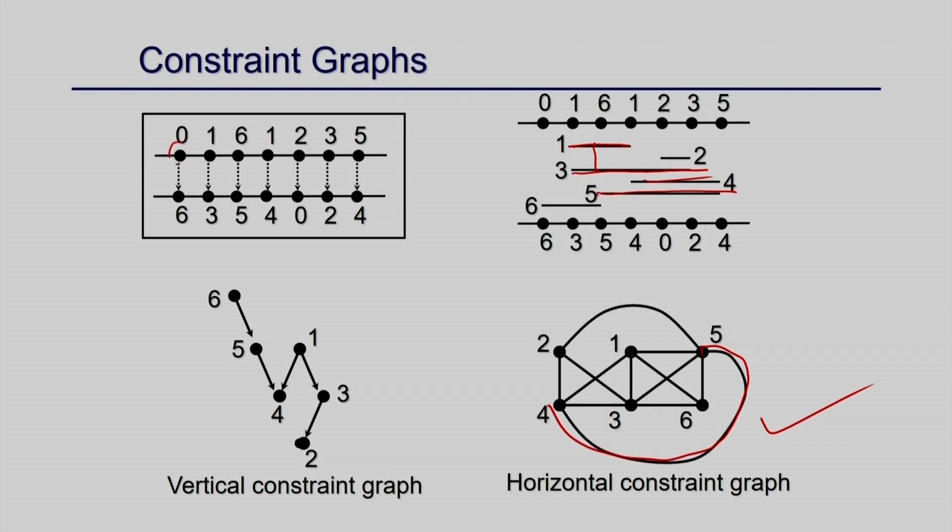Similarly, there are connections that do not cross in the horizontal line, right. What I am trying to say is that if 6 is there, say 1 to 3, right, 1 to 3 there is a connection. So that means whatever the connection is happening, say 1 to 1, this 3 cannot go here, right. So you cannot go across this. So if this is the track, say 2, the connection from 3 has to happen below this, at least. From 3 it cannot go crossing this, right. So that is what is called a vertical constraint.